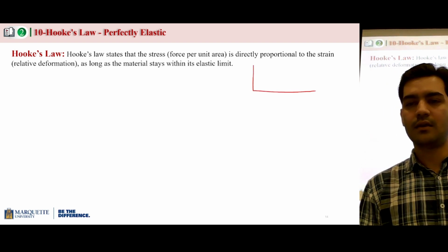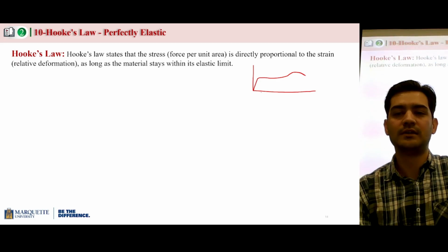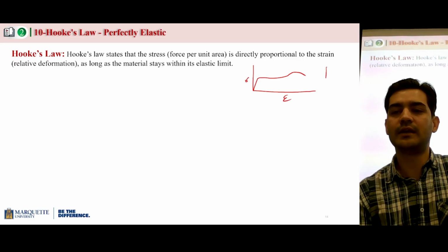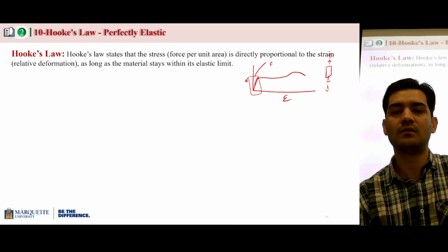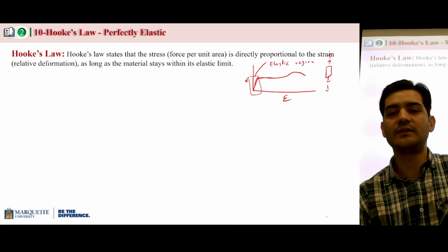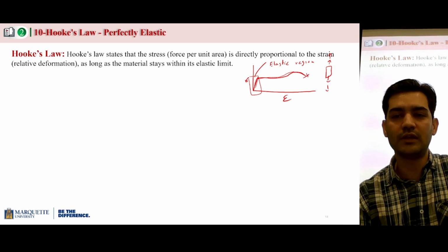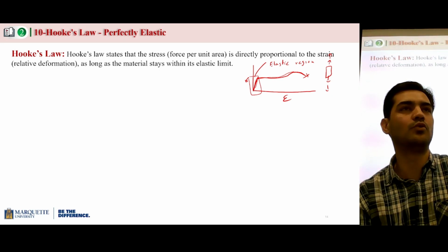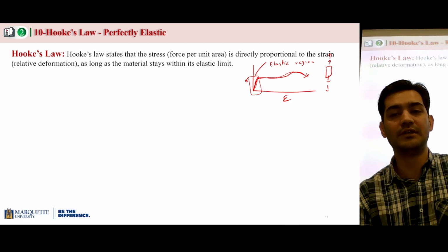So we have already seen the stress strain curve for different materials. We know that if we keep increasing the force slowly, we see an increase in stresses and strain up to a point, and this region is called the elastic region. After that, you have the plastic region, strain hardening, ultimate stress, and then fracture. But we are only concerned about the elastic region. So we will not go beyond it. We will not apply forces which will extend the material beyond the elastic region.